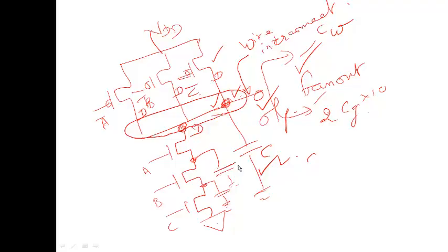Whereas the capacitance in between is due to the source terminal of this device and the drain terminal of this device. This node is generated, and therefore whatever the diffusion capacitances are, those would be added here.